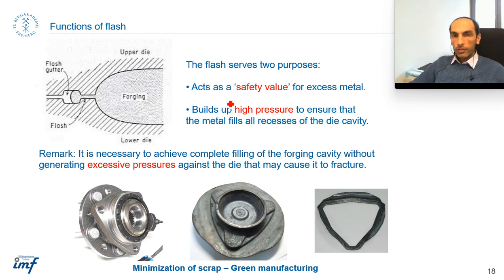the flash first acts as a safety valve for the excess material. I said that in the design stage, by simulation we obtain the size of the initial workpiece or initial billet, so we can be sure how much of the cavity will be filled by the material. However, in practice, sometimes the billet size may be a little larger.